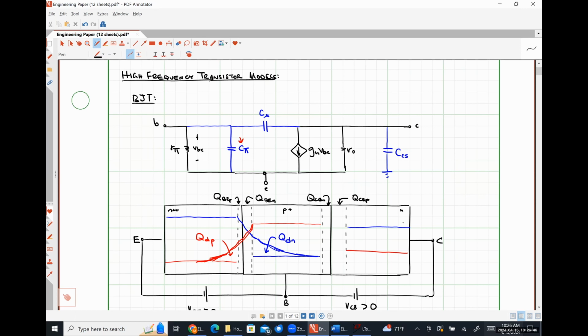Because some of them are for sure going to be in the midband, but several are not. Right. That process could literally be true for anything we ever wanted to look at. By the way, we know, hopefully, at this point as electrical engineers, that damn near any signal can be decomposed into a sum of sinusoids and all that kind of jazz. And so then we could just look at it frequency by frequency and map what's happening. And that is literally the frequency response of the circuit.